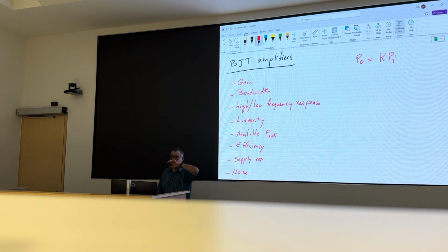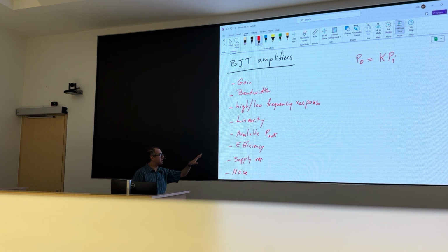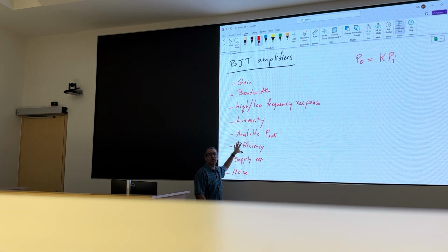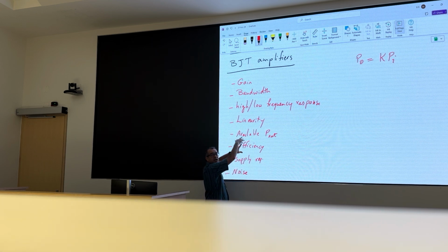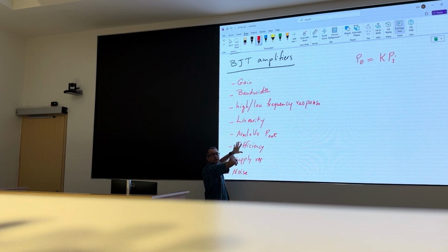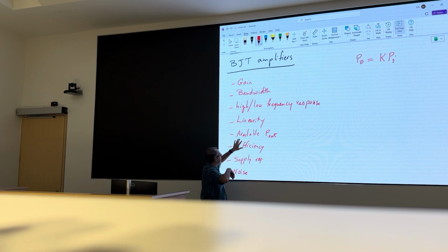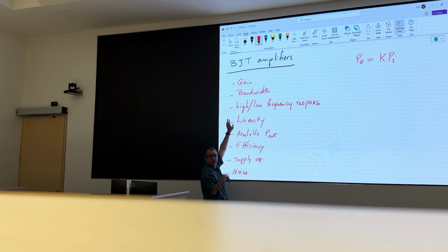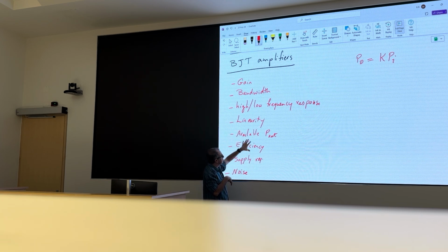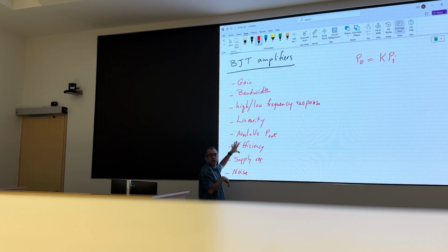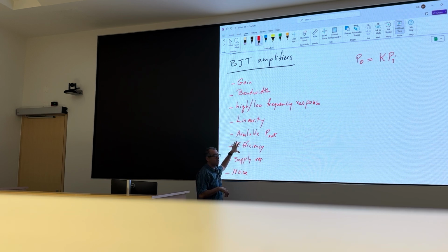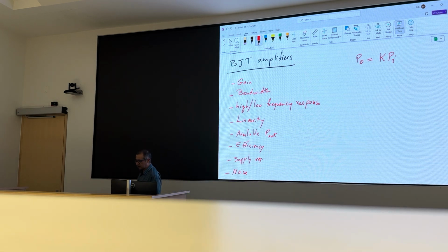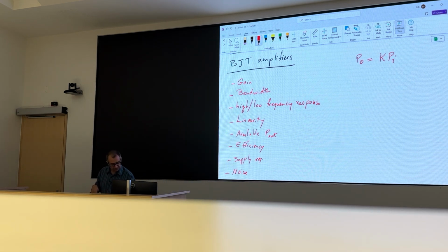The only time that it may happen is if you sacrifice power or efficiency, then usually you gain in a lot of those other areas. If you consume more power, you usually have better linearity, better noise performance, you might have better bandwidth, right? So this is the only one that usually improves a bunch of parameters at once, but this is usually the one that you don't want to spend, right? Because you're running everything off of batteries.